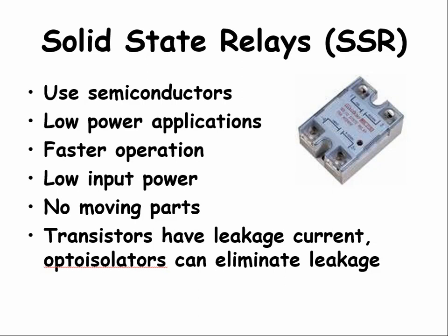The other disadvantage of solid-state relays is that some may have what is called a leakage current. A leakage current is the current flow that continues to pass through on the load side of the circuit, even though the control side of the circuit says to open the circuit. Leakage current is inherent in semiconductors. Leakage currents may not be a problem with some loads, but if leakage currents are a problem, they can be managed with opto-isolators.